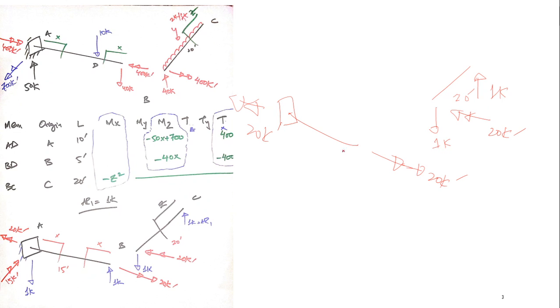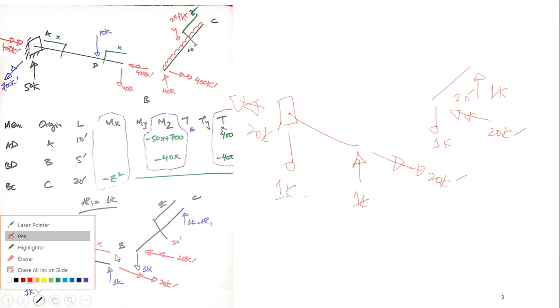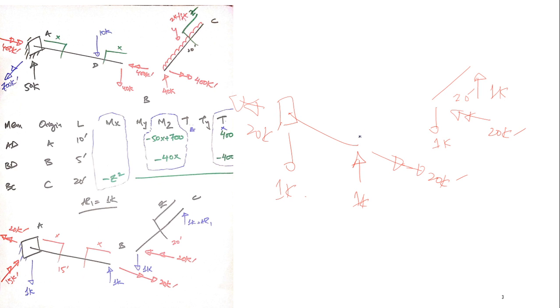I've done here. This joint has to be balanced in terms of loads: 1 kip and 1 kip. Finally, this is forming y, this is x, this is y, z. There would be a moment in z. This is forming an anti-clockwise moment, and this would be clockwise. This is 15 feet, so this would be 15 kip foot. You can see, it's very easy. So I have drawn the free body diagram.